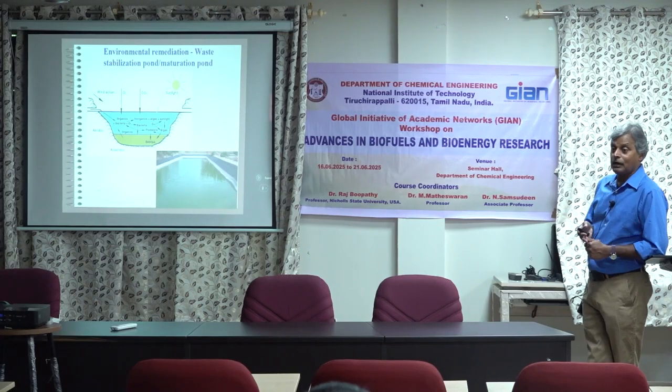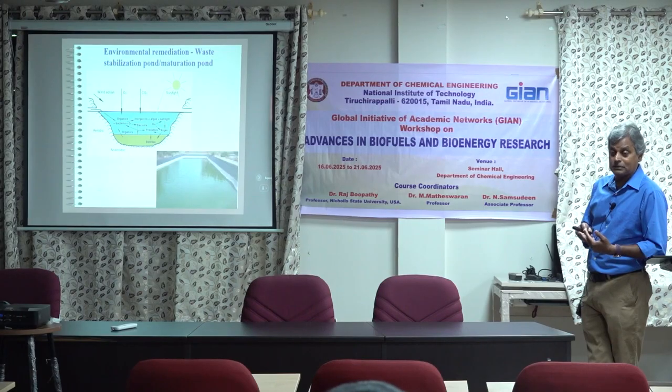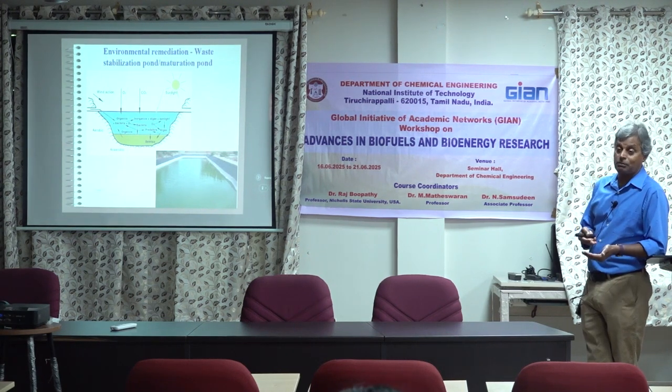We can also use algae for bioremediation. If you have wastewater treatment, one of the input costs is aeration, to aerate the pond system for aerobic bacteria, because oxygen is your limiting factor. When you have a lot of carbon, the aerobic bacteria are going to consume the oxygen fast. Then you need to put more oxygen into the pond. That is an added cost to your treatment system. You have to use electricity pumping oxygen into the big pond system.